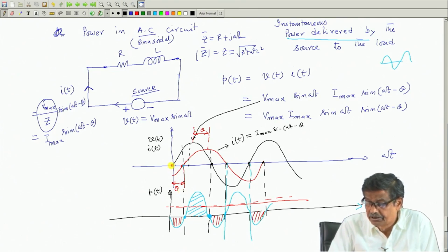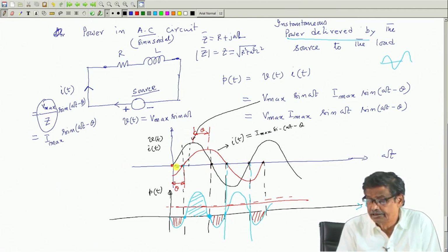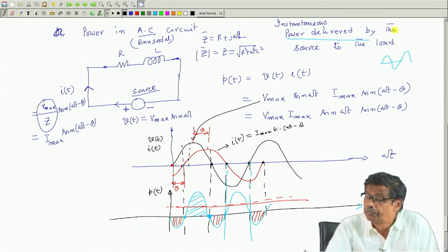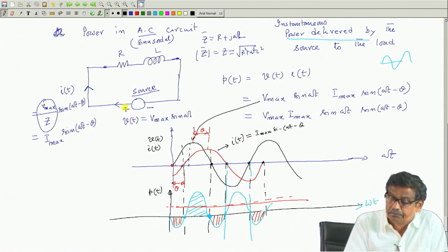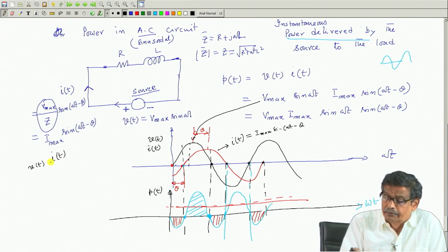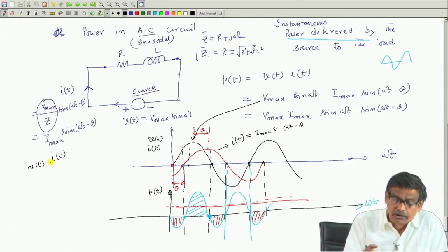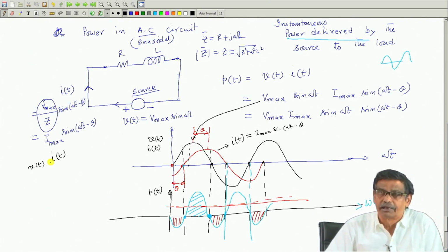following this rule. Wherever a zero crossing has occurred, both for voltage and current, you mark them with bullets, draw vertical lines and say during this period voltage is plus, current is minus. So, negative power, but I am calculating power delivered by the source, because this is how I have assumed it, as if it always delivers power. So, v(t) into i(t), mind you, gives you power delivered, but in a scenario like this, this product will sometimes become plus, sometimes minus.